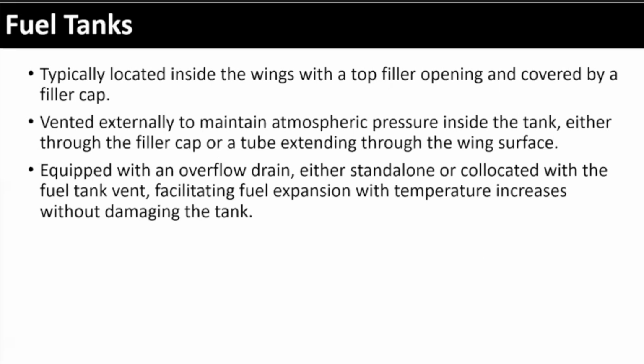What happens to fuel when it gets hot? It expands, right? If you've got full tanks in your airplane and you're sitting out on the ramp in 100-degree weather, what's going to happen to that fuel? If you don't have vents or drains for that fuel or that vapor to escape from, what's going to happen? It's gonna blow, right? Something's gonna go horribly wrong with that fuel tank. So they're designed so that as that expansion happens, there's vents to allow the gases to vent.